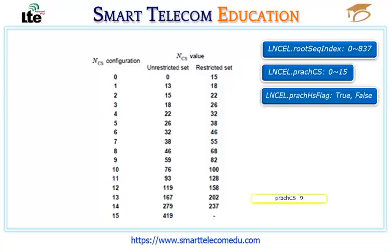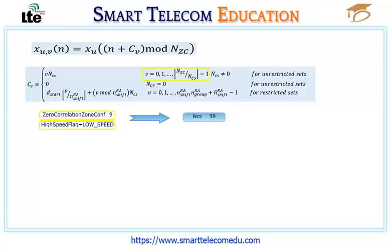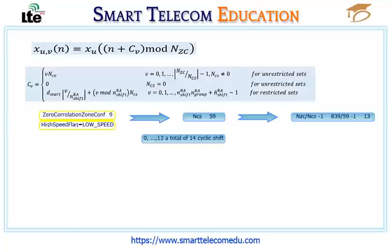For example, the PRACH CS parameter equal to 9, and the PRACH high-speed flag is false, then the NCS value is equal to 59. The maximum number of cyclic shift that can be used is from 0 to NZC divided by the NCS value, minus 1. In our example, the NCS value is 59, then the number of cyclic shift is from 0 to 839 divided by 59, minus 1, that equal 13, so a total of 14 cyclic shift that can be used for the first generated sequence 37 in our example.